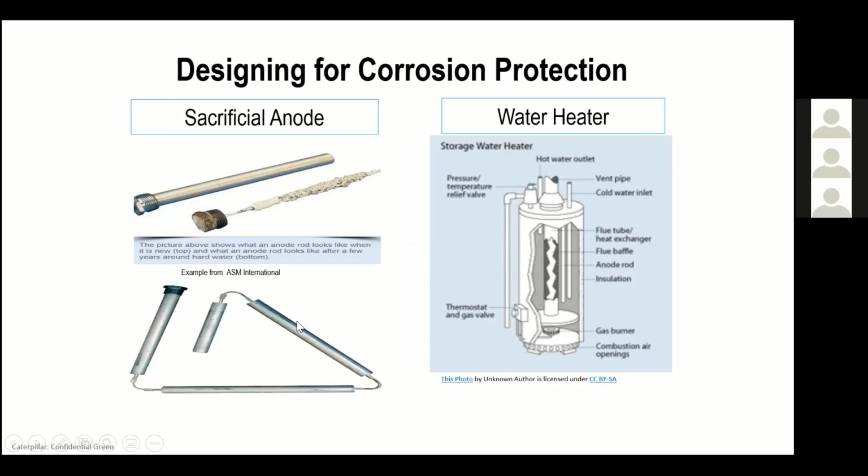I prefer, because of the headroom in the houses that I've owned, these flexible sacrificial anodes that you can buy. They're a little more expensive, but you can replace them very easily. You might have to cut the other one out because you don't have enough room to pull it out, but you want to replace it if you have headroom space. So it's just a way for you to be smarter than your parents, or explain to them that you have an opportunity to save them some money down the road, because you can really extend the life of those water heaters.